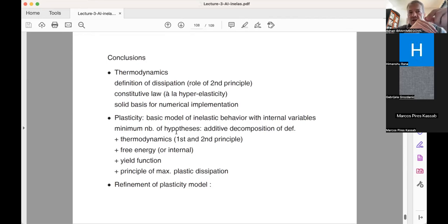That means at time t you are plastic or damaging, and at time t plus dt, if you want to keep doing that, then you have a contribution of the plastic multiplier or damage multiplier. That allows you to do this computation by asking that the time derivative of the yield function or the time derivative of the damage function be equal to 0.